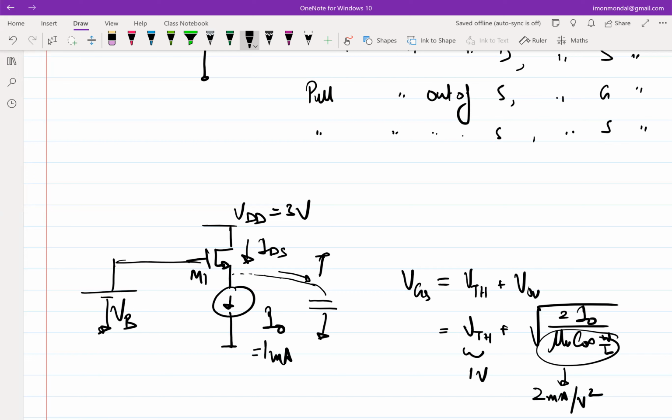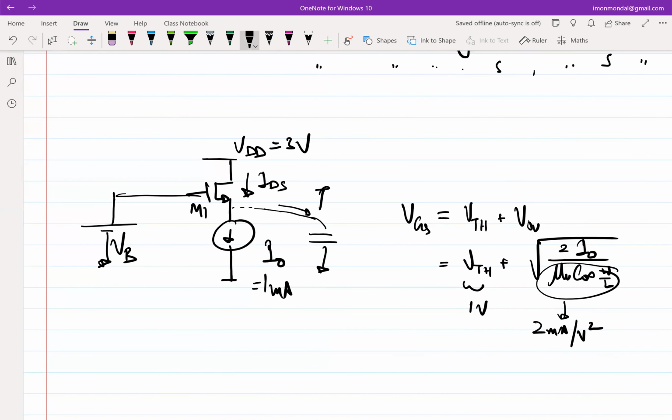2 volt higher than Vs. That's good because VGS is equal to 2 volt, under the condition that I gave you, VGS has to be 2 volt. So it has to be 2 volt higher than the source. So what is the source voltage? VS has to be less than or equal to 1 volt.